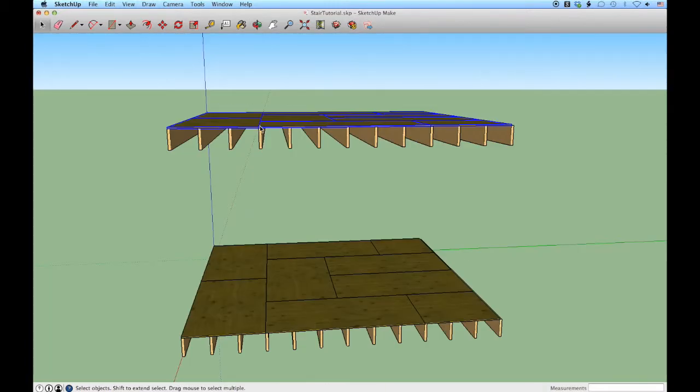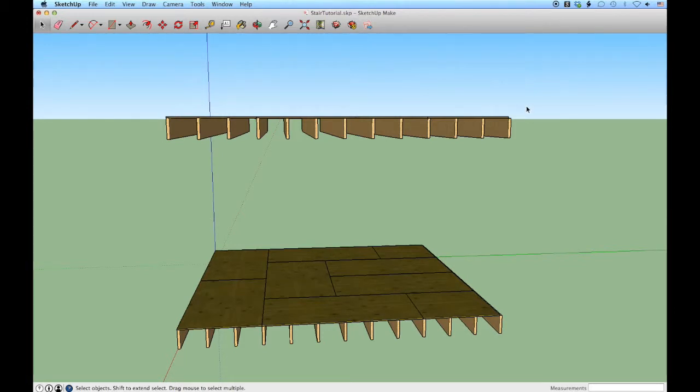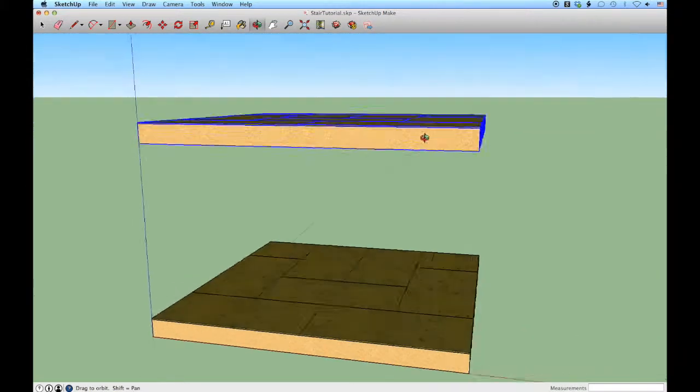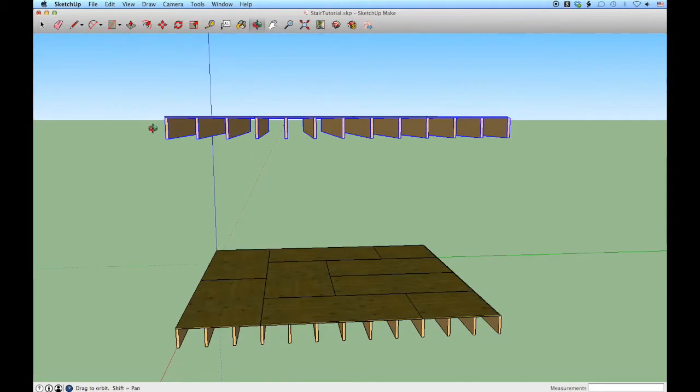Now I'll show you the difference. Let's go to spacebar and click outside and deselect. Go back to where we were and you start on the right side and you click and hold and drag and you try to do exactly the same thing where you just come down about halfway. It doesn't matter that you came down halfway. Everything that the bounding box touched gets selected. So you can see that the floor joists and the plywood are now selected, and that's not what I really want to do at this time.